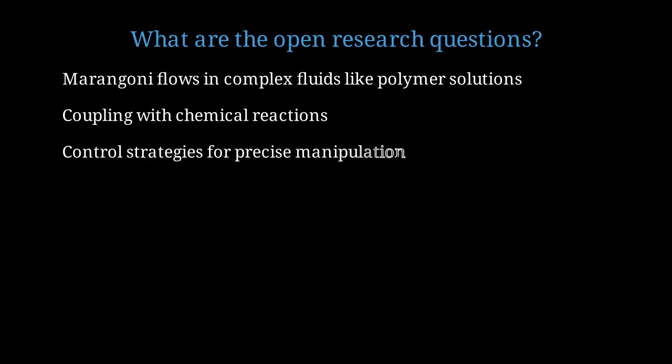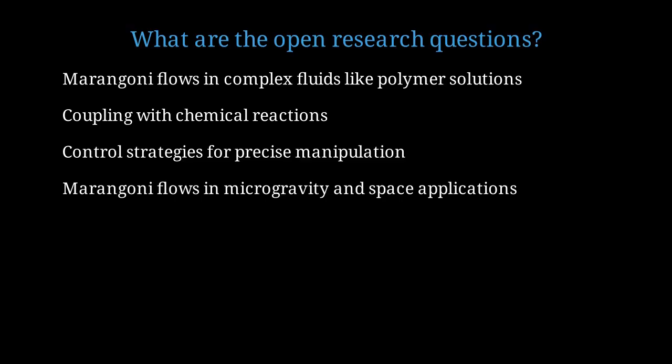Can we develop sophisticated control strategies to precisely manipulate droplets or particles using spatially and temporally varying Marangoni stresses? In microgravity, buoyancy-driven flows vanish, making Marangoni effects the dominant mechanism for convection. Understanding this is crucial for materials processing in space.